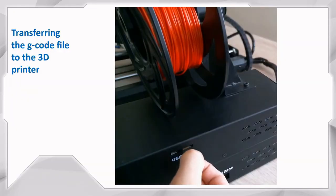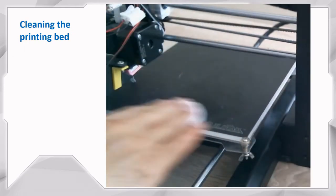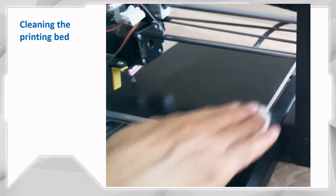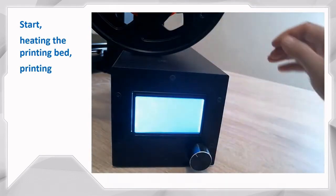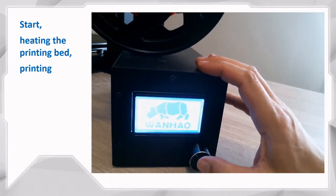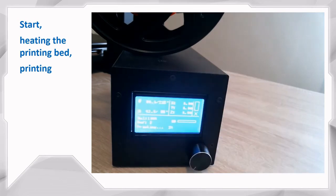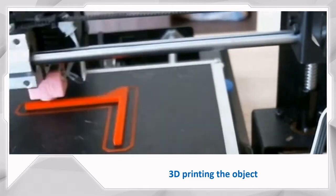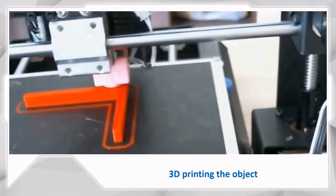Next, the G-code generated by the slicer needs to be transferred to the 3D printer. Before starting printing, we need to clean the build surface. Now we can start printing. The printer will take some time to heat the printing bed and the extruder to the set temperatures. Once the set temperatures are reached, the 3D printer starts building the object, layer after layer.